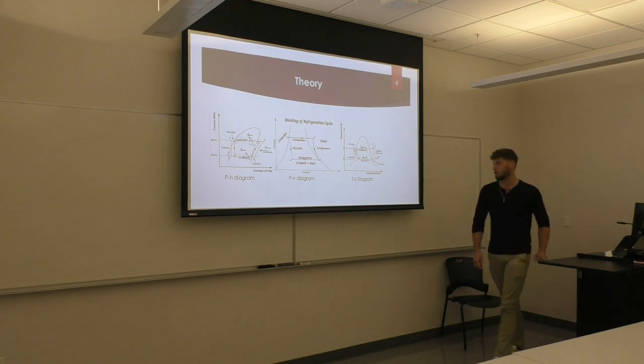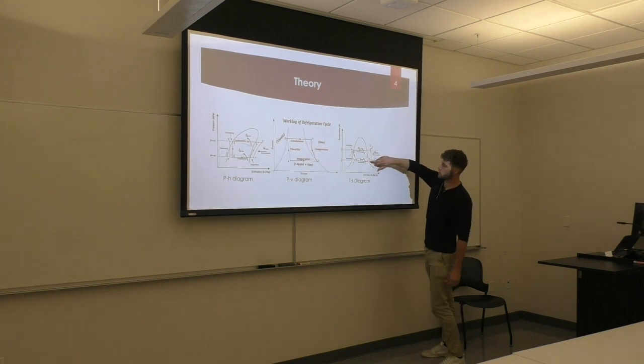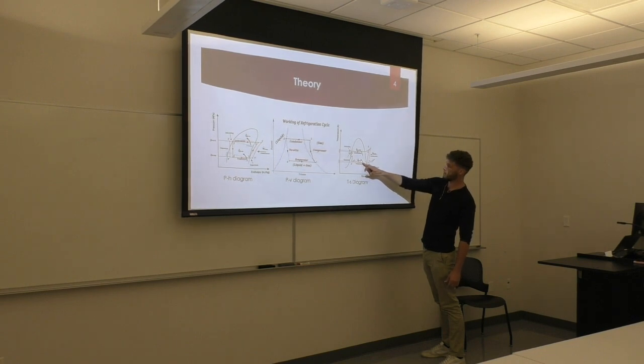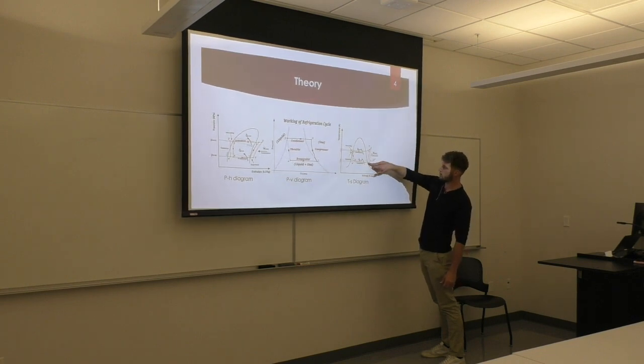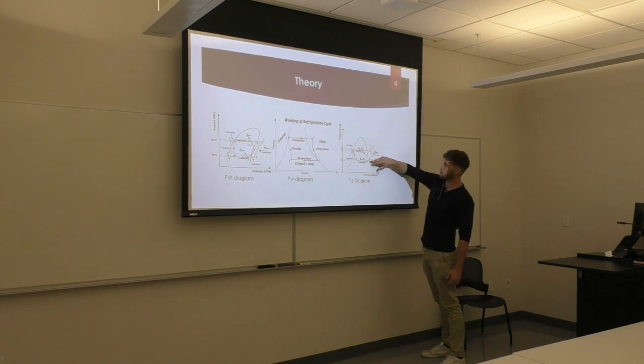So going based off what we know, we'll start with the compressor. You have your compressor, it starts at just barely a vapor. It works across a saturated mixture as you go across, but right when it reaches a vapor, for efficiency reasons, that's when you enter the compressor. You don't want any liquid in the compressor because it breaks compressors, we know this. It moves it up to superheat.